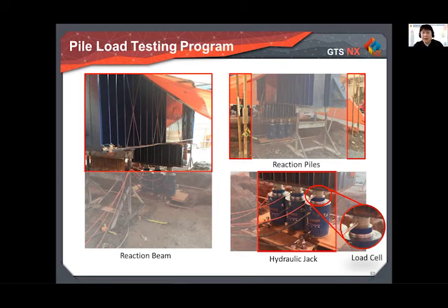The geotechnical design starts with the design of the pile load test. So we define the type of pile, the diameter, the length, the maximum test load, and also the reaction system. We followed up the execution of the test and later interpreting the result.